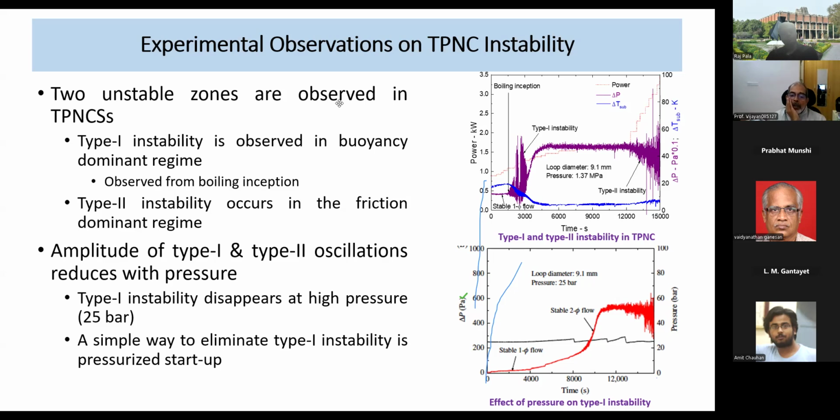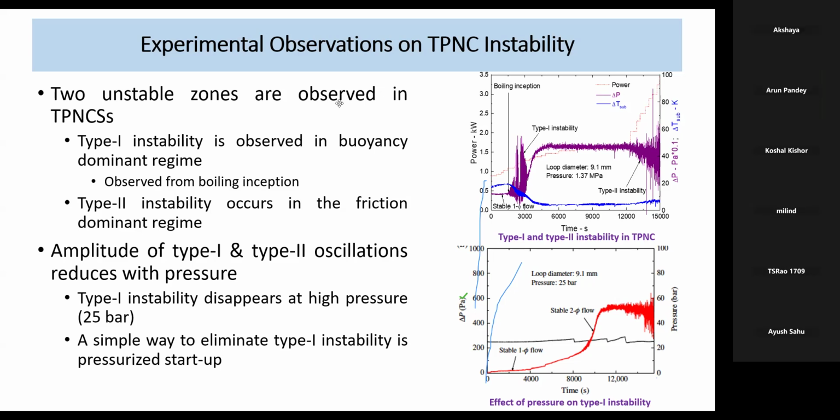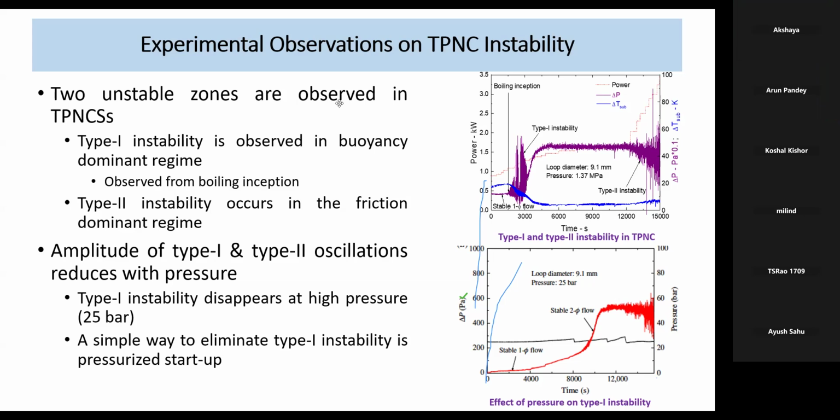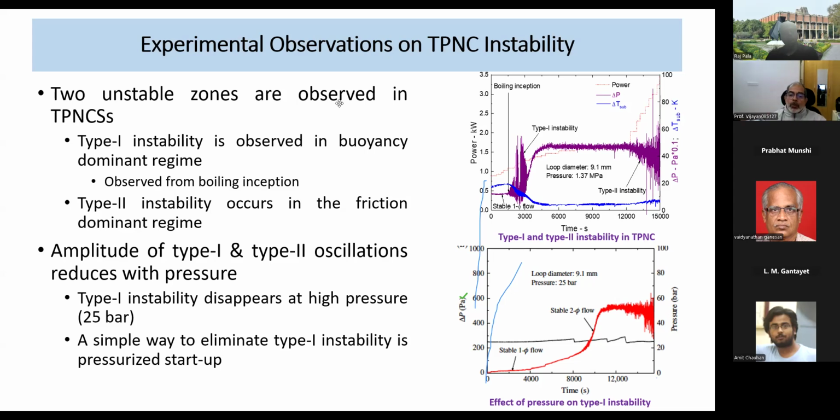And the only way you can increase the power rating is, as we were telling, to go to that integral type. We found you can have very high flow rate, so we were working on one small micro modular reactor. Even for a power of about 15 megawatt thermal, we can get about 900 kg per second flow, which is quite high, so those reactors can go to higher power. That is, their L by D is very less.